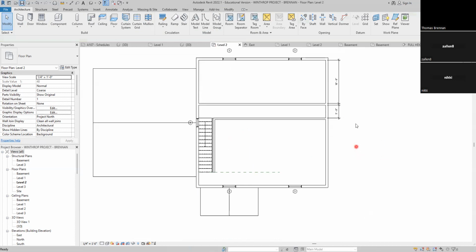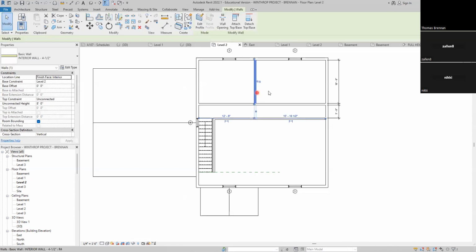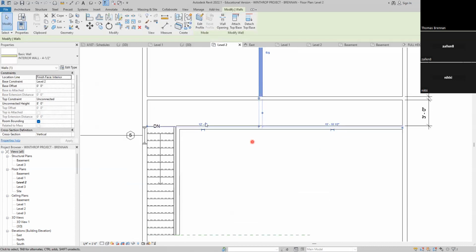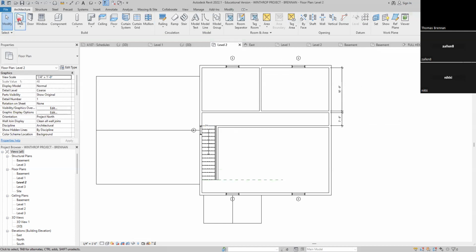And then the next thing I'm going to do is now that I've got the basics, the next thing I have over here is my vertical walls. And they're 13'1" on each side. So I'm just going to go here. I'm going to start here and do the first one. Now just see what the dimension is there. And that's not quite 13'1". So I'll do this 13'1" like that. And it moves it over like that. And I'll do the same thing over here.